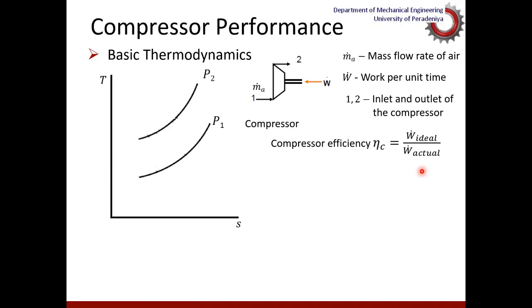And if you look at the T-S diagram, this is the intake to the compression, and this line represents the pressure at the outlet of the compression. So this is the pressure boost rather. So we want to increase the pressure from P1 to P2. And if you consider an ideal process where there is no heat transfer, so an isentropic process, so there is no change of entropy, you can go from state 1 to state, let's say, 2 prime.